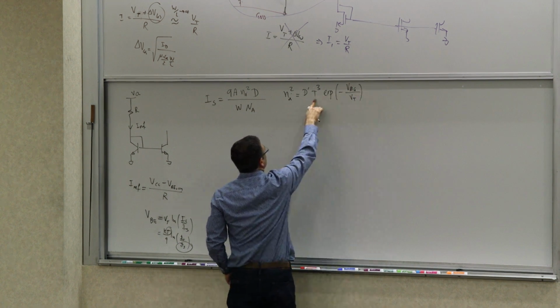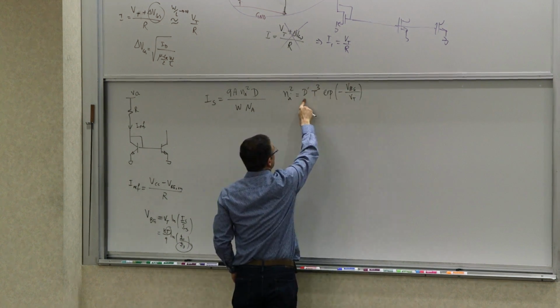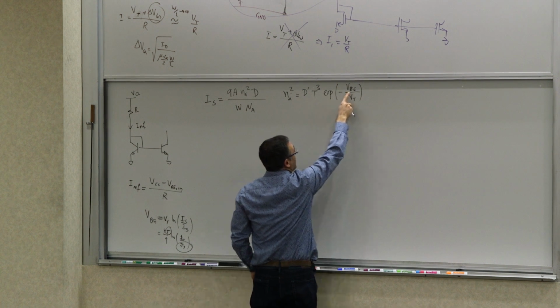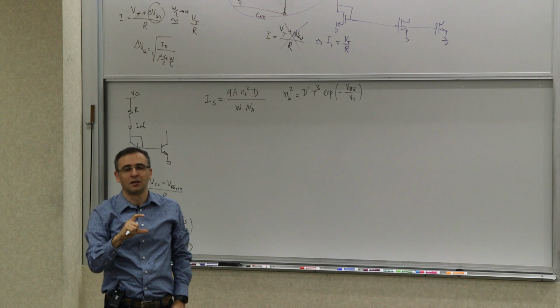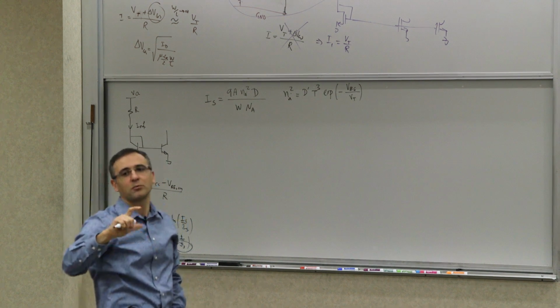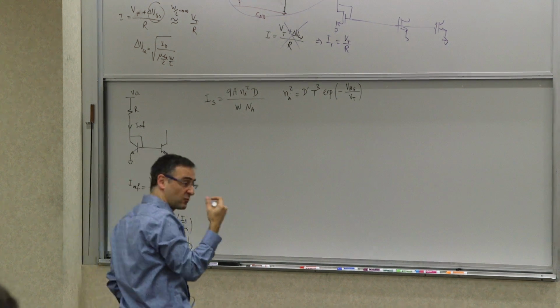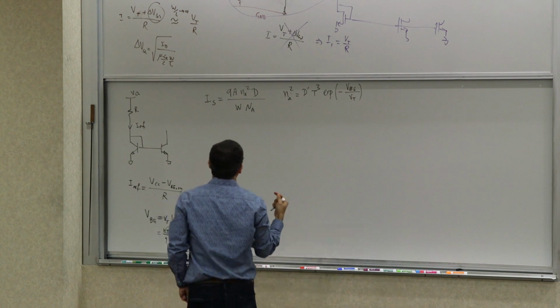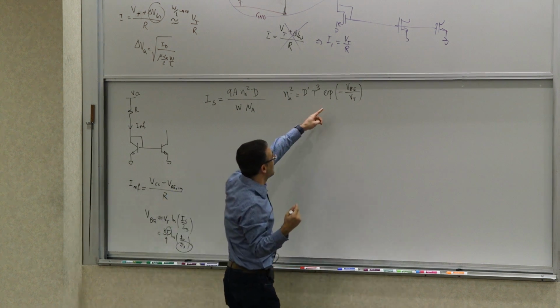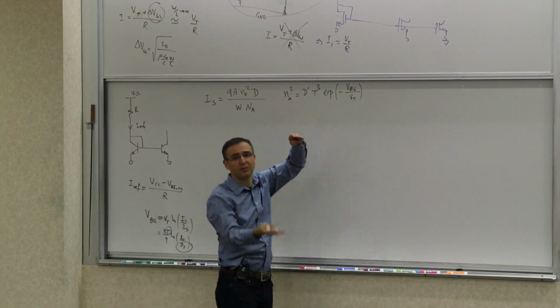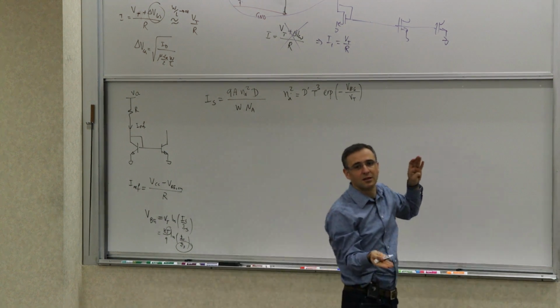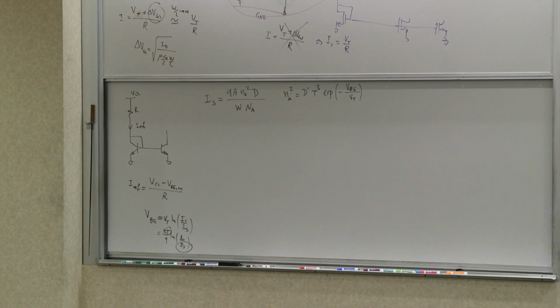Now, T is the absolute temperature. This is some proportionality constant. Now, VG is the band gap voltage of the semiconductor. So in the case of silicon, it's about 1.1 volts. And it makes sense, right? Because the larger the band gap is, the smaller the intrinsic concentration would be, because these are thermally generated electron-hole pairs, right? So that dependence makes sense.